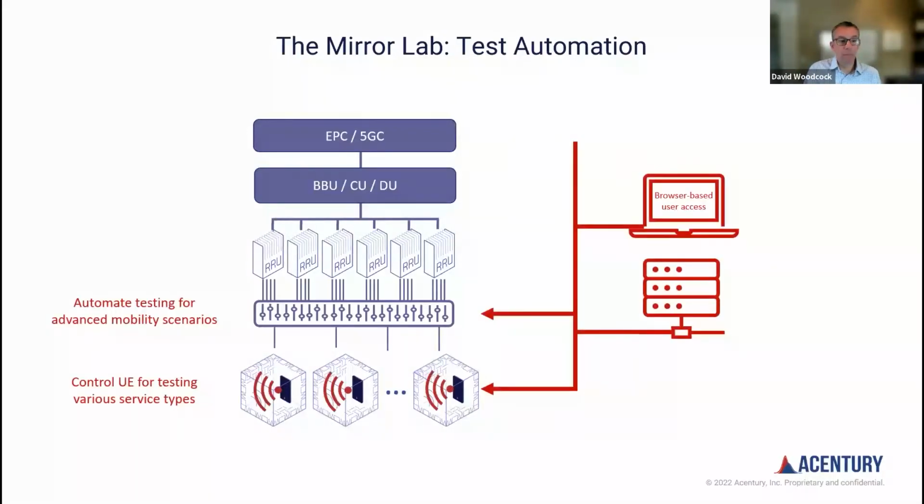Next, the various call types are automatically started on the devices under test, and the RAN equipment broadcasts signals into the RF switch matrix. The orchestration layer controls the RF switch matrix to execute the RF portion of the tests without human involvement. Various call types are made under different RF scenarios like roaming, handover, different orders of MIMO, and carrier aggregation by controlling that RF switch matrix.